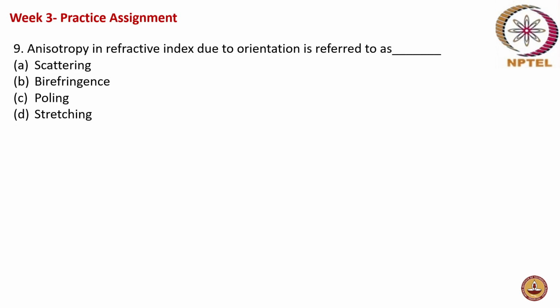I showed the answer also. Oh, actually, I can't see. Okay, then it's good. So tell me what that is. The professor mentioned that due to the stretching, anisotropy happens, and we can characterize this orientation by using birefringence. Yes, it is birefringence. Because of the anisotropic nature, your refractive index in the different directions will be different. So this phenomenon is called birefringence. Okay, and this is a measure of the orientation.